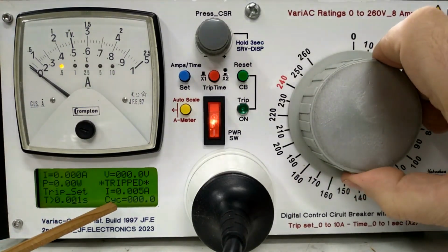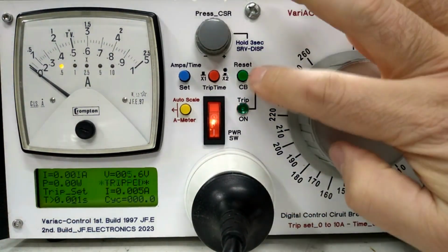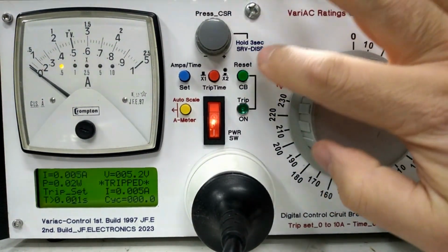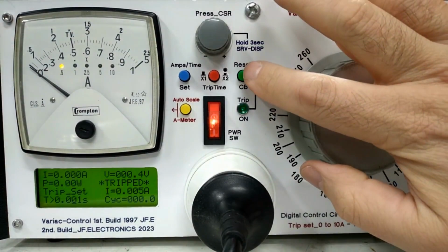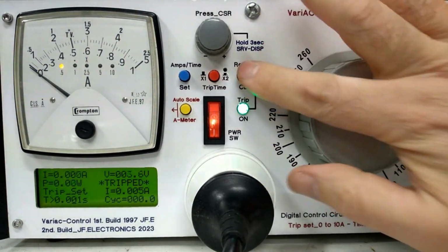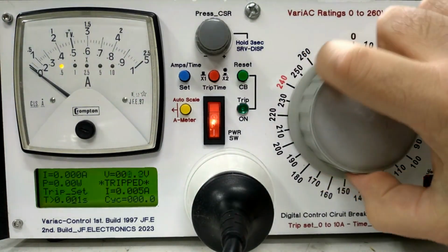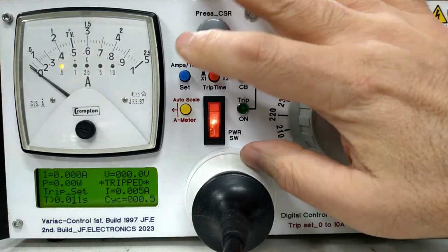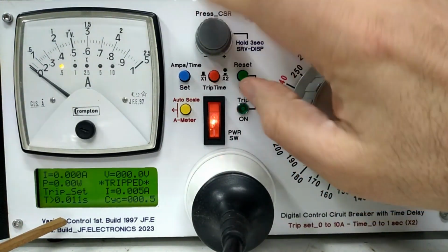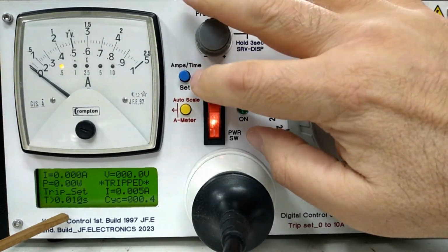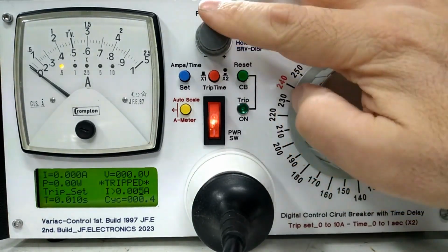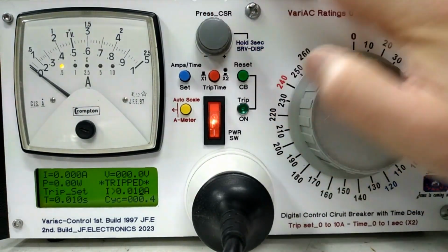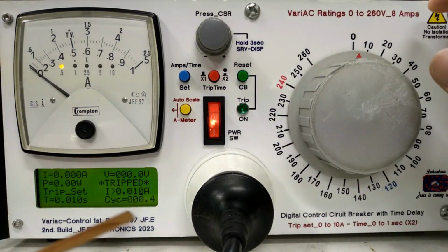So if I turn up the voltage a little bit more, okay, I'll go a bit more. There you go. It's because the current is taking that little bit to reach. So I've put up the voltage more. So let's do a, okay, I'm still in the time settings. Have it at 10 milliseconds. Change the time delay, the current now. Let's go to 10 milliamps. Okay, so I've got 10 milliamps, 10 milliseconds.